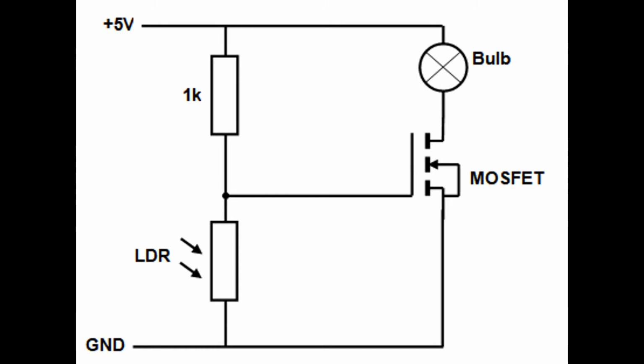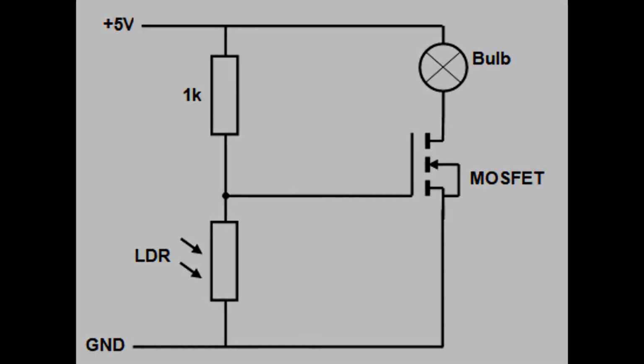The Schmitt trigger would clean up our response to use the MOSFET in either off mode or saturated mode, depending on the LDR being strongly lit or not, removing the dusk light middle ground that causes partial conduction. I will do a separate video about Schmitt triggers very soon and MOSFETs. However, for a very rough and ready circuit, it shows you how the gate voltage rises as it gets dark and the drain voltage drops as the MOSFET switches on and the load increases.